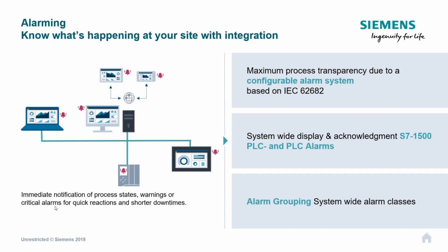Okay, so this means that then when we generate an alarm, it's generated at the controller level and then pushed out to the HMIs, which all have the capability to read this alarm in as a textual format and display those alarms. This gives us some great benefits. So all of the timestamps and things like that will be synchronized based on the controller's timestamp, not the individual timestamps at the respective HMIs.